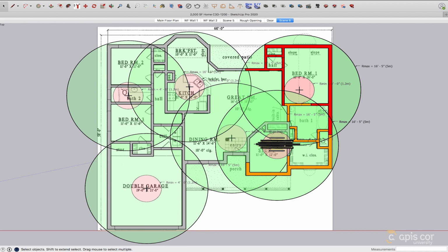Although this portion of the wall could have been printed from the first position, we will purposefully wait to print this portion from the second position to avoid trapping the printer inside of the first room. After printing section 2, we will move to print position number 3, seen here in yellow. Here we will print the extra walls which were inside of the minimum print radius at position 2 in the study room. Then, we will move to print position number 4, seen in green. Similar to section 1, we will wait to print a portion of the wall between the kitchen and hallway, which will allow us to easily drive the printer to the next position.